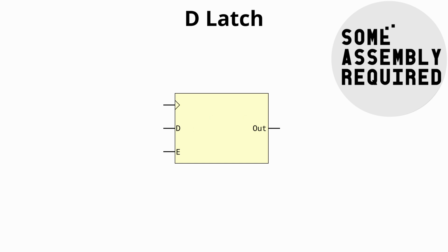Being sensitive so long as a line is 1, or for that matter 0, is called level trigger. Being sensitive only to the change is called edge trigger. So a flip-flop is a latch that is based on an edge-triggered clock. So finally, this is a D flip-flop.